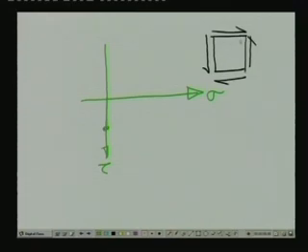The perpendicular plane, which is at an angle of 90 degrees, in the Mohr's plane will be 180 degrees, where again normal stress is 0 and we have negative shear of equal magnitude. So, these are the 2 points on the Mohr circle, and since sigma x and sigma y both are 0, eventually this will be the center of the Mohr circle. So, if we draw a circle with the center at this particular point and radius from O to A, we get the Mohr circle for this kind of stress which is acting.